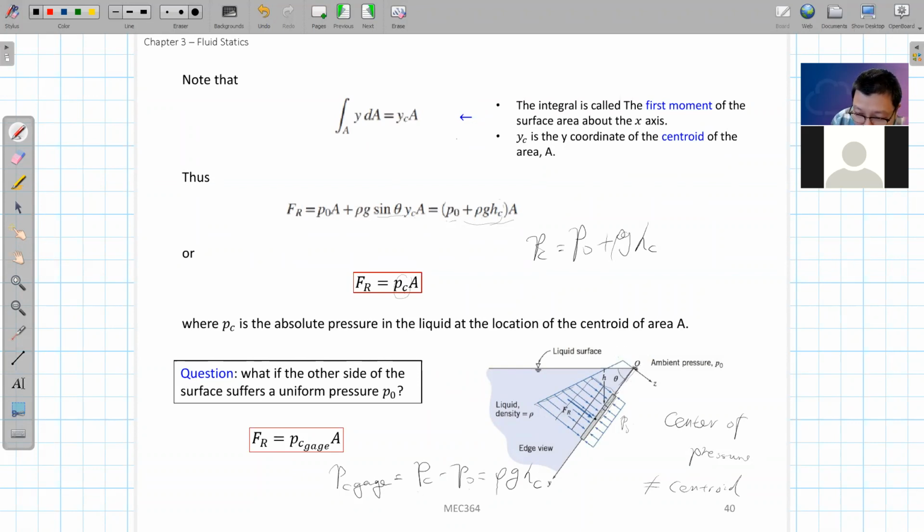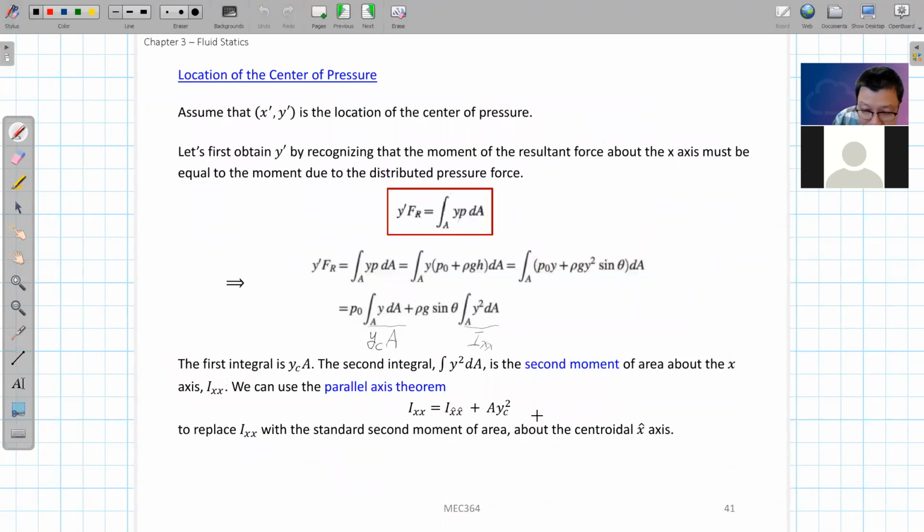Now we want to move that x-axis to the centroid of this location here, okay? With the parallel axis theorem, we can calculate this new Ix, this x-hat with the height on the top, okay? Ix hat is basically the second moment of area about the centroid axis. By doing it this way, we can convert this correlation into this one here.